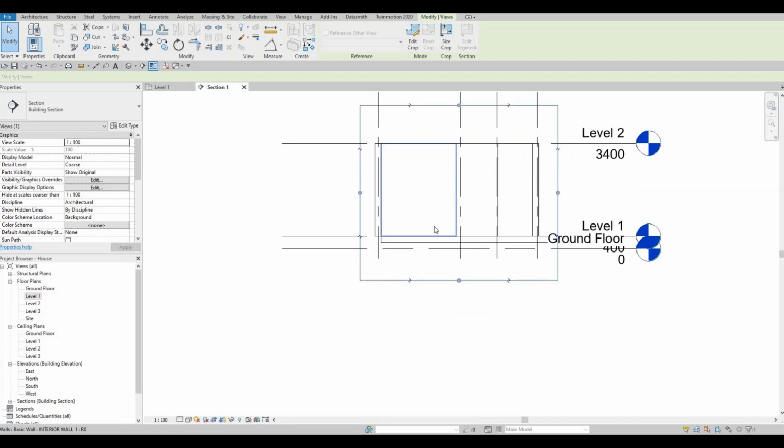And because we're going to add a floor as well right here, we're gonna maximize the height to 2800. So from floor to above, this will be 2800, because we're gonna subtract the floor that we're gonna add onto our second floor on level 2.